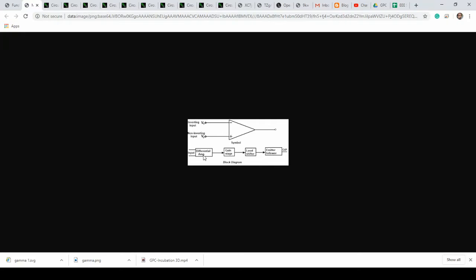Looking at a block diagram, it's actually made out of transistors. So it's a differential amplifier. There are two inputs, both the signals are amplified, and the difference goes to the next stage. Now you increase the gain of the stage here, then you shift levels. If it's less than 0, you go negative. If it's greater than 0, you make it positive. And if it's exactly equal, you set it at 0. This is level shifting. Then you have an emitter follower to couple the stage to be able to drive your outputs. So that's your output line. This is the block diagram of your operation amplifier.